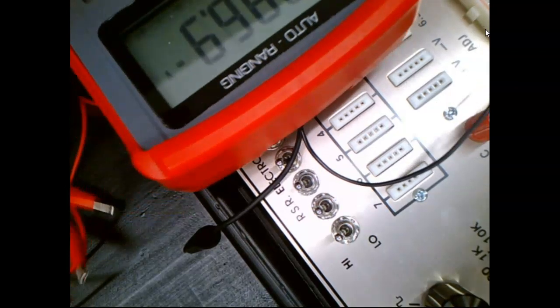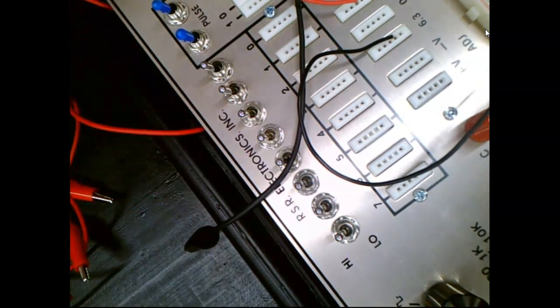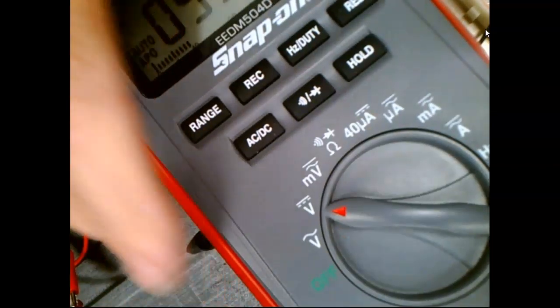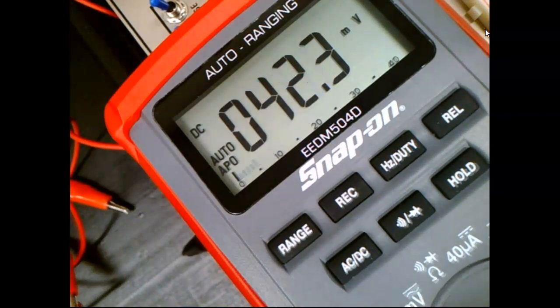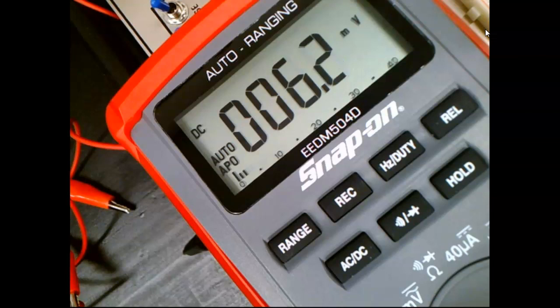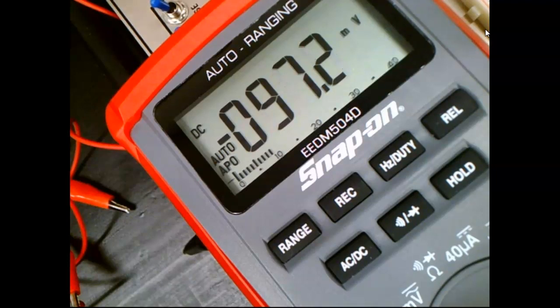And this gets people hurt, right? You understand why? Because they don't think about what their meter's on, and they'll come across here and they're measuring an AC source, and what does it show? It's going to show 0, right? Six millivolts, that's pretty close to 0. I get that from here, right? Well, AC induces voltages in everything. So I measure more up here than is actually in the circuit. It's almost hard to make an AC meter measure 0 on a small scale like this.